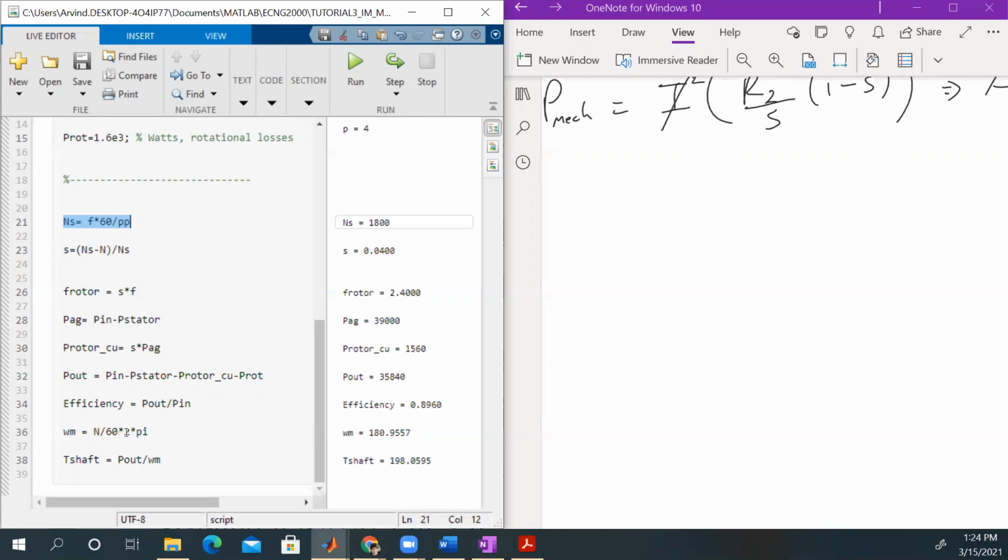Right, so what we're looking at here is when we were finding the synchronous speed and using the pole pairs, the speed we were referring it to, to find the slip, was a mechanical speed, but we had the electrical speed. So the pole pairs help us go from the mechanical to the electrical and vice versa, right? So the electrical speed is one thing, and the pole pairs translate that into the mechanical speed. The electrical speed is from pole to pole, whereas the mechanical speed is actually physically on the rotor.